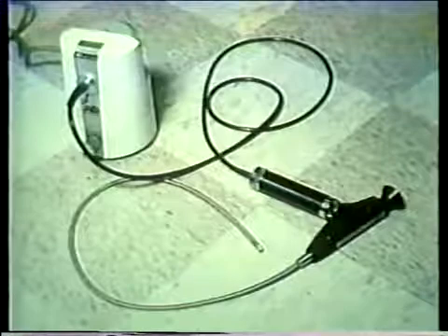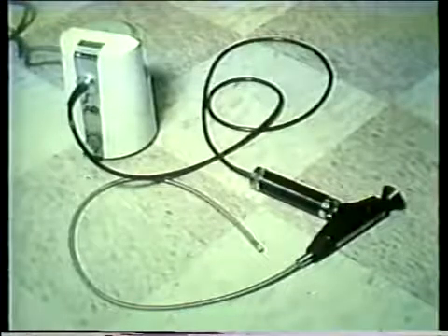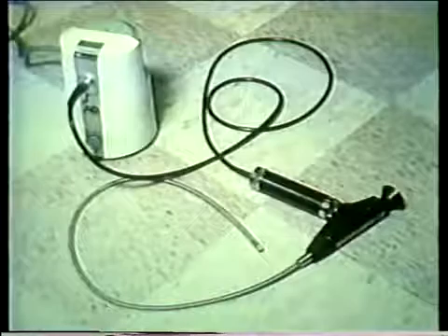Because of access problems, the borescope becomes an important inspection tool. We already mentioned that a borescope is an instrument that uses glass fibers called fiber optics to allow you to see around corners. Well, this lets you examine header and tube areas that you normally can't reach. For example, if a header has no handholds, or if the handholds are welded in place, you may still be able to inspect the header and some of the tubes. You can do this by taking apart a valve that is close to the header and then running a fiber optic through the valve and pipe into the header.